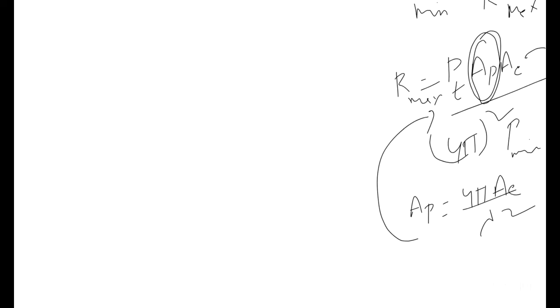P1, P2, P3 are for the transmitter part. Next, for the receiving part, you will get P4 as well as P5. After reaching P4 and P5 for the receiving part, I give the conclusion that if power is minimum, range is maximum. From this, I calculate the final value of R maximum. So this is the fundamental form of the radar range equation, 18.10.